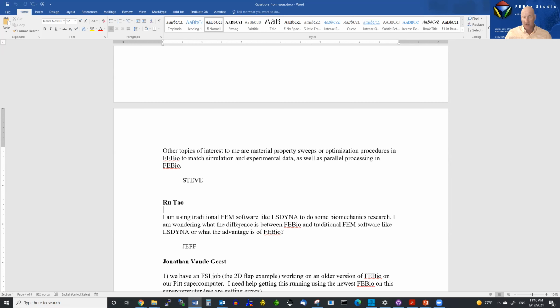And so typically that results in taking time steps that are on the order of microseconds, sometimes smaller, for engineering materials. And so generally speaking, codes like LS-DYNA that use explicit time integration are designed for events that occur over very small pieces of time, like fractions of a second. Some of the classic examples are things like automobile impact or ballistics, explosion of weapons, those kinds of things. That's why this technology was originally used at Lawrence Livermore.